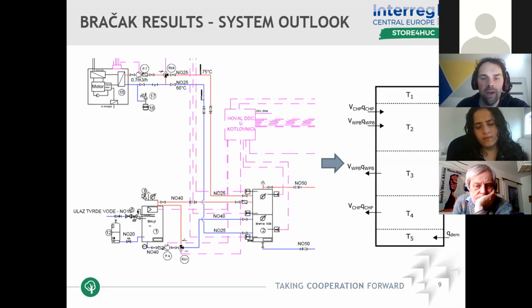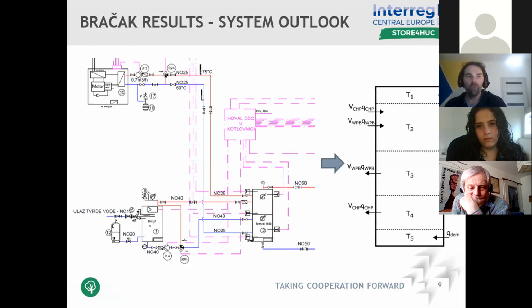What should be the temperature at this particular level in the storage where the water is sourced from for the CHP? If this temperature is overstepped, then CHP can no longer operate, cannot provide the heat, and this is bad from the point of view of economy of the plant at the end.